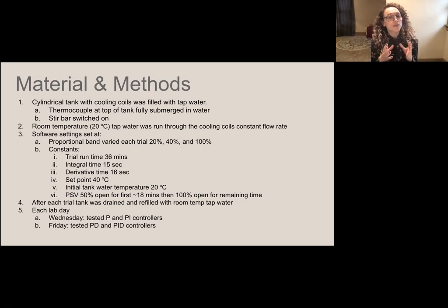And then everything else remained constant. So the trial run time was 36 minutes. The integral time was kept at 15 seconds, derivative time 16 seconds. The set point temperature was 40 degrees Celsius. So it's increasing from 20 degrees to 40 degrees.